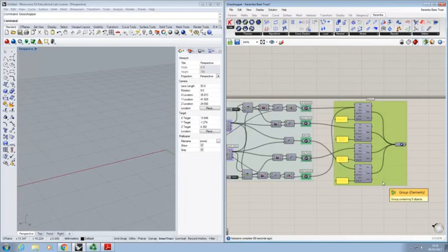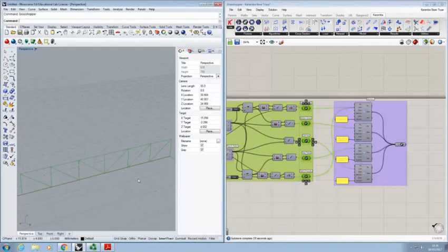So next up, we have to set up some supports for the truss. In this example, the supports are reasonably important, but not very important. If you have an arch, the end conditions become more important. Nevertheless, if we only support the end of the bottom chord, the model is going to be unstable, and it would want to spin in a rigid way around the bottom chord. So ideally, we support the end 4 points.